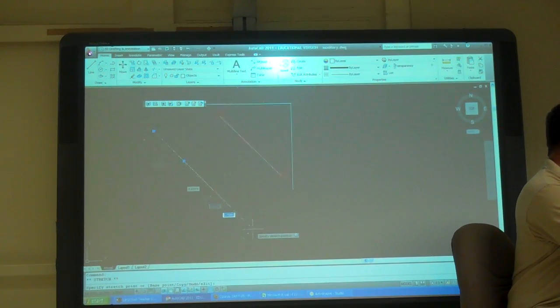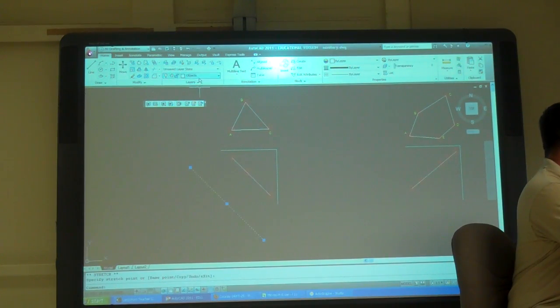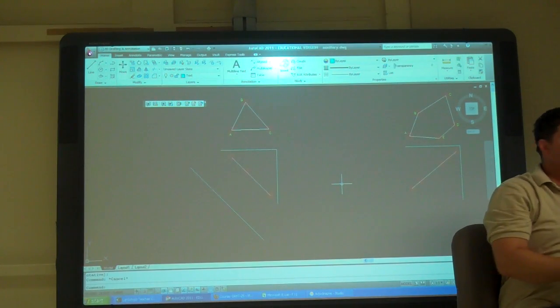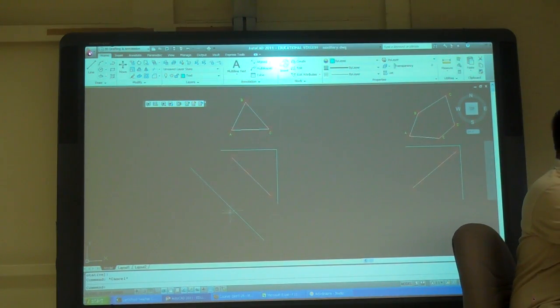And I can pull it down past the part that way. Turn it into a folding line. Okay? So just use your grips and stretch it out. Use the extension so it stays straight. So I have it now.